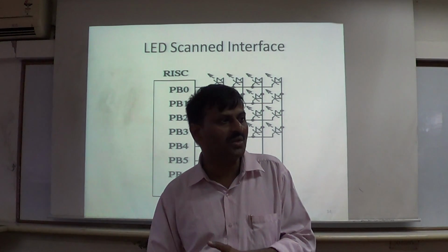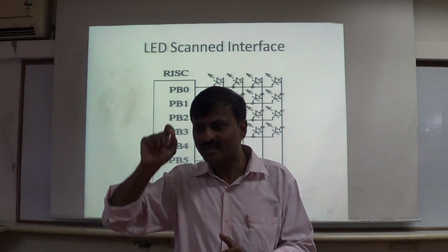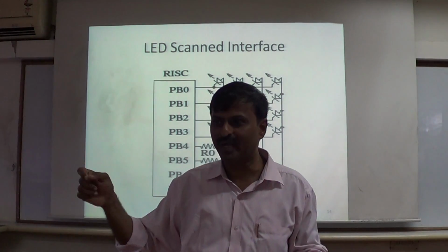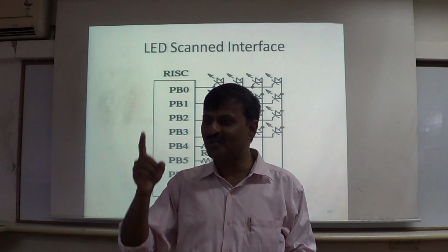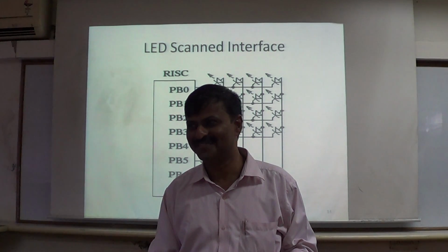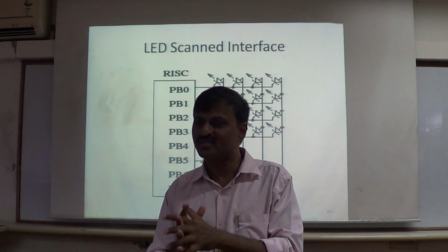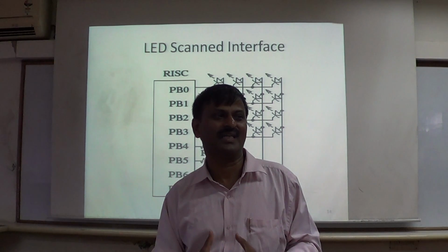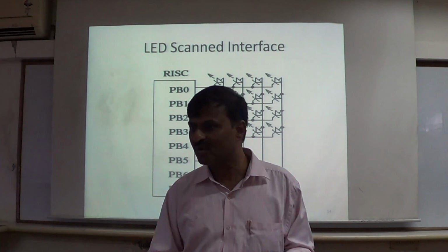And we do not want to display the data in microseconds of time, so it's okay. We can quickly switch on this, then this, then this, then this, and again I will come back. You feel as if a beautiful text is displayed, but as a matter of fact, only one LED is on at a time. Okay, so that is how scanning is happening. These are all scanned displays, scanned controllers.